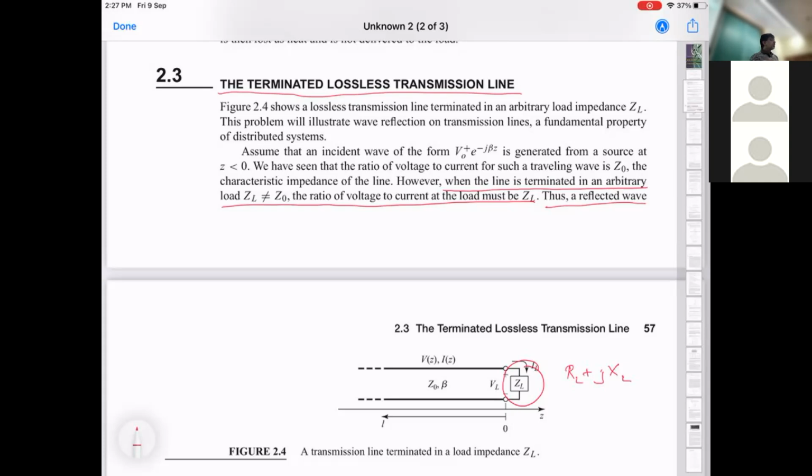Connected to it, here it looks like 2 wires, but these 2 wires represent a transmission line model. What we want to understand is how this device looks if I connect some other things to these 2 points. Instead of connecting directly at the device, where I know that it's an impedance ZL, I do the same thing over here with this intervening transmission line, whose properties are characterized by these 2 numbers and the length.